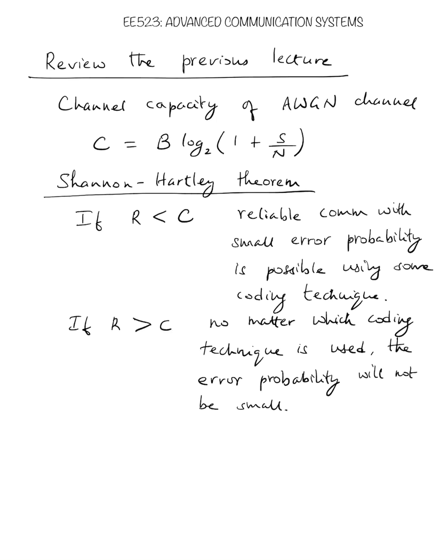And we have seen in the last lecture the effect of increasing bandwidth, because the noise power depends on the bandwidth. If you increase the bandwidth, the noise power is going to increase, and therefore for a given signal power, the signal to noise ratio will decrease, and so on. We discussed all of these things in the previous lecture.